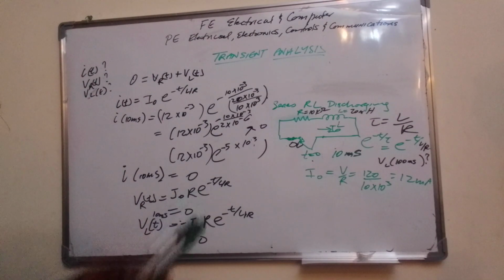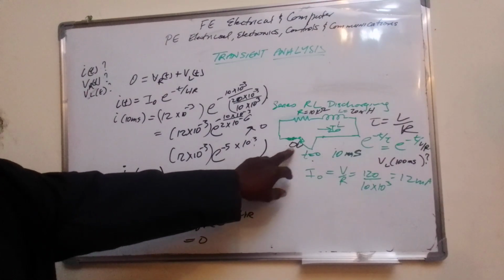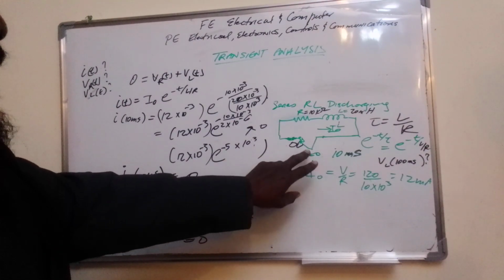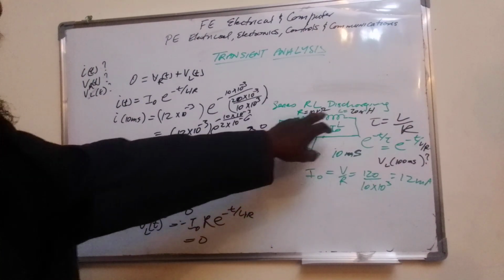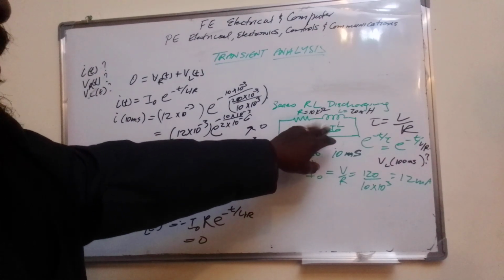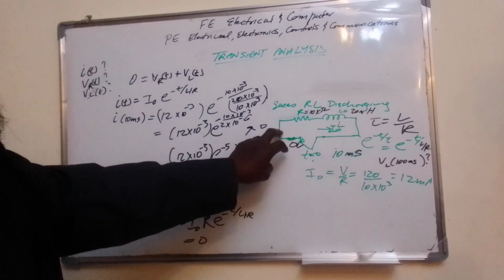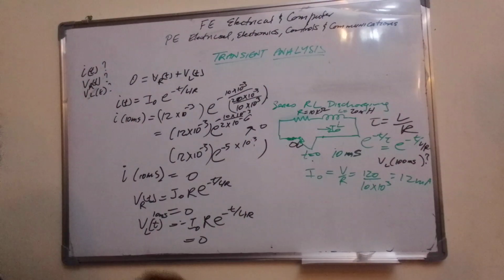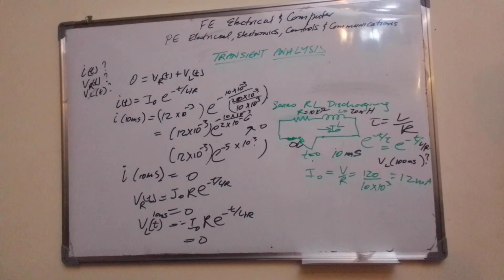It took us a little while to see that, but you have to realize this is a discharging circuit, and once you close that switch, whatever energy was in the inductor, supplying through the resistor, will already have discharged through the resistor, and the voltage across the resistor and the inductor at that point would have been 0.